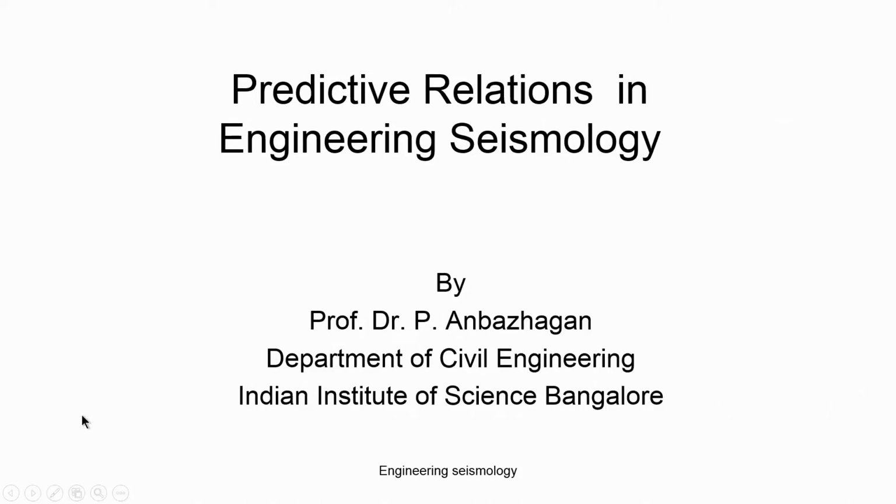As I told you, last class we discussed the predictive equations in engineering seismology. We also discussed the stochastic simulation model, and we have seen that you can generate synthetic ground motion data. Those data are generally used for getting the acceleration time history and velocity, and thereby you can also go for developing a ground motion prediction equation.